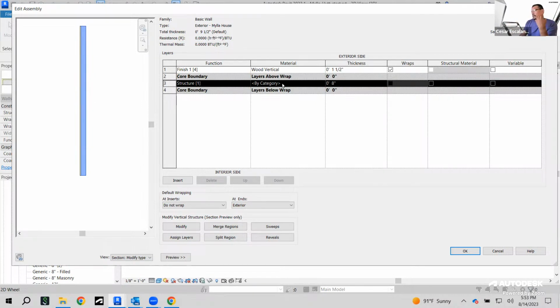I think last class I talked to you about what object styles is: a global setting of materials in Revit. And most of the time, 80 to 90%, we don't define materials per category because the rule is too stringent. Imagine every structural framing has a single material. That's not realistic in any project. And so for the most part, the materials remain empty. The material and the object styles remain empty. But by category means that it's going to read the global setting.